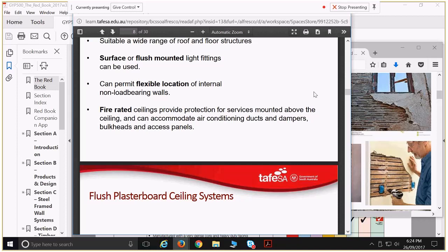Possibly aesthetics is not an issue, but because we're dealing in increments of 300, 450 or 600 millimeters, we want our rooms to be of those dimensions as well. Otherwise, we end up with half or a third or even a random percentage of a tile left over at the end.